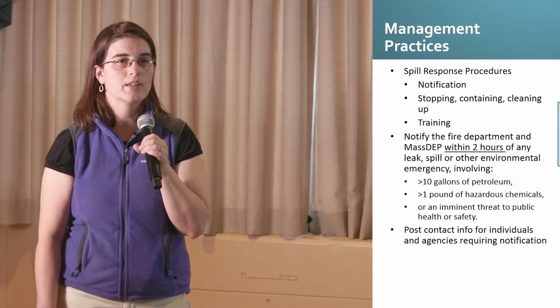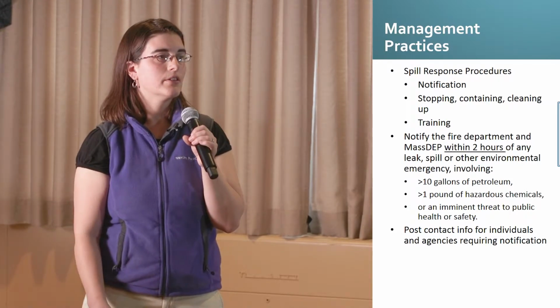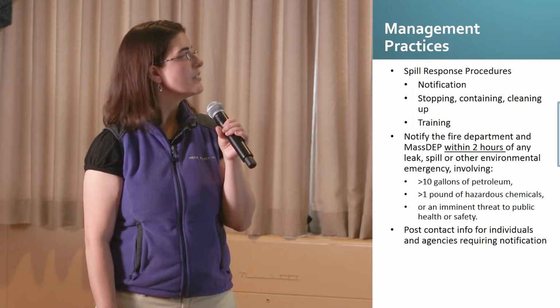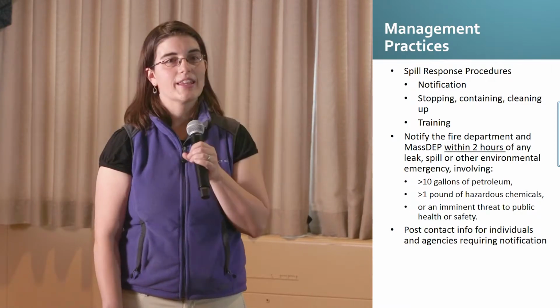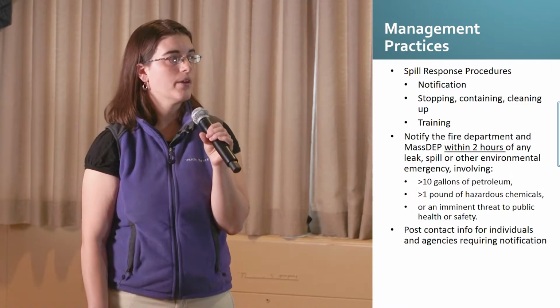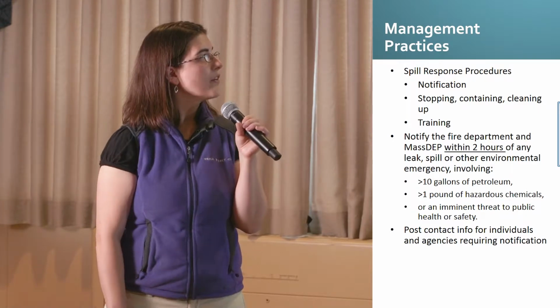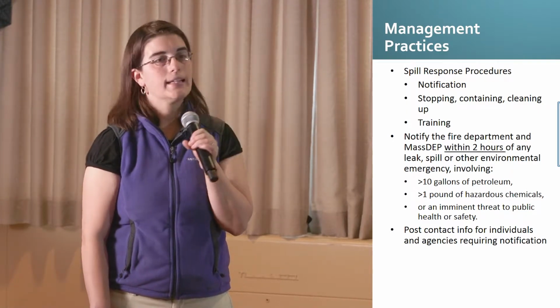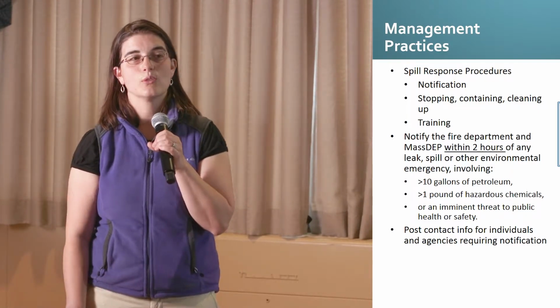So for spill response procedures, they need to be outlined in your SWP or referenced in your SWP. And they need to include notification of who you're going to notify when there's a spill, how you plan on stopping, containing, and cleaning up the spill, and also needs to include training.